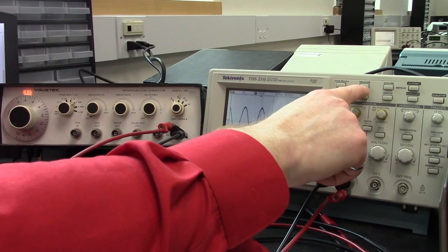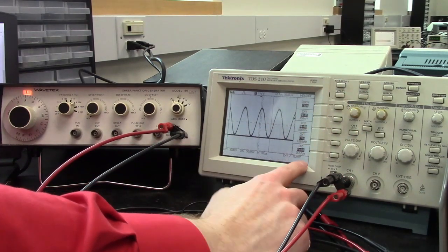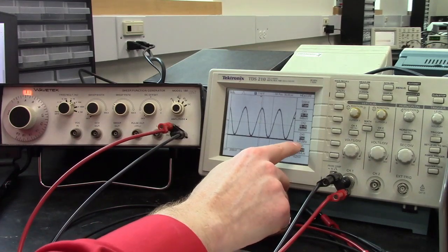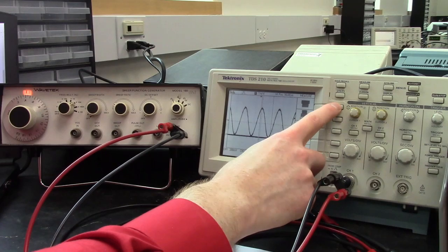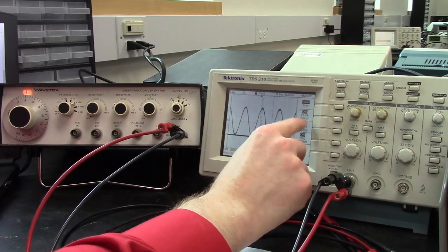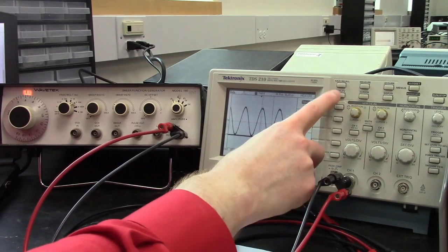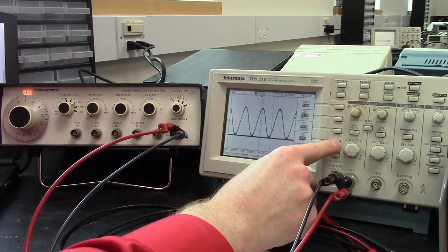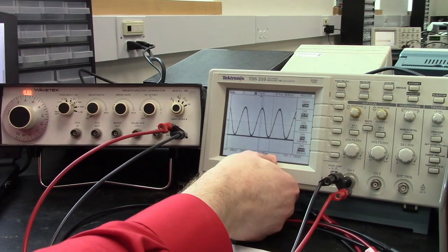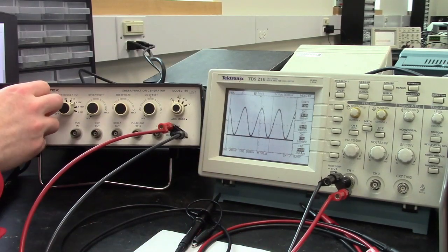So we'll hit this button, and then what you can do is set up all the different measurements that you'd like to see. So we already have it there on the screen, channel 1 frequency. If you don't have that, I'll show you how to get it. So first click the source button here, toggle this to set the source, change the channel to channel 1, and then toggle that again back to type, and change this around to frequency. So now we're at frequency. We can see the actual frequency right now is 3.87 kilohertz.